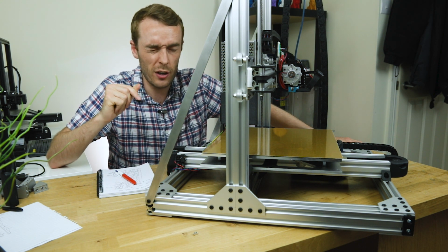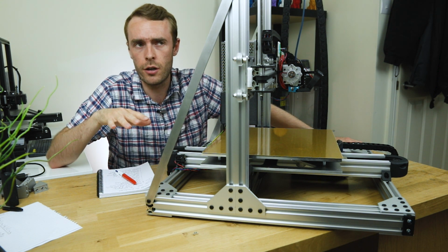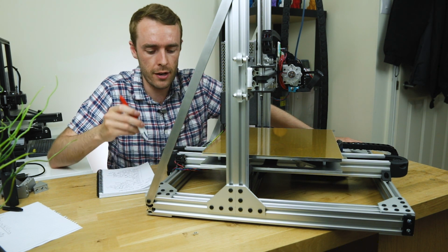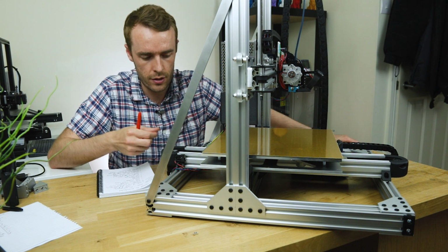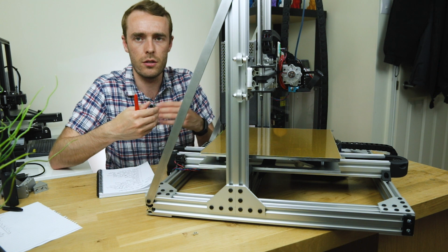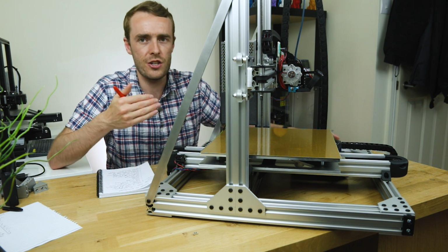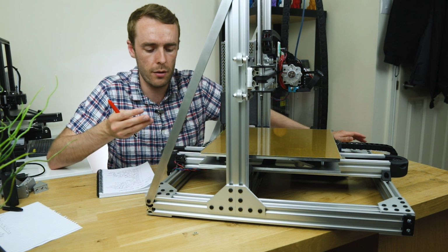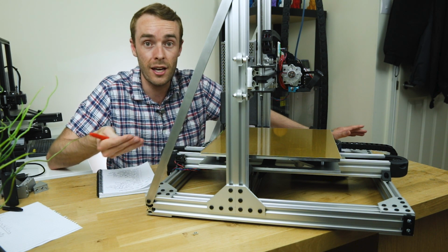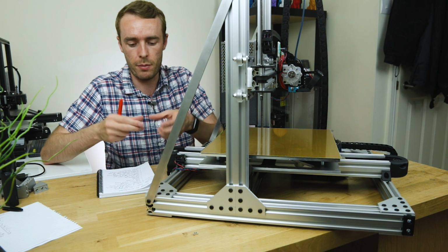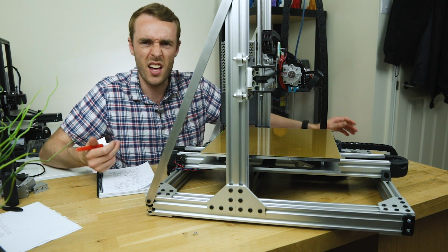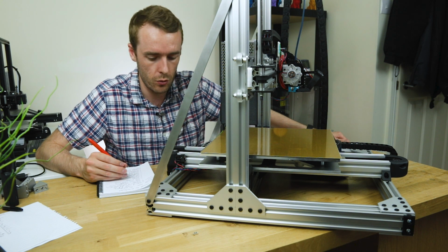Now, I'm not exactly certain why a larger tooth profile would help, but I'm fairly sure it will. So I think what it will reduce is the chance of the belt skipping over the teeth due to high acceleration. Now, I've not actually seen a problem with that, but I think what I'm likely to find is just larger, thicker belts just come with larger teeth anyway, because a larger, thicker belt will not bend as much, so you have to have larger teeth. I think that's probably what this is going to all come round to.